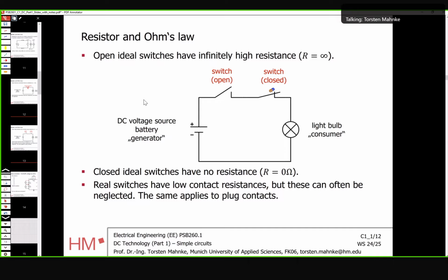This resistance was dominant. All the other resistances in the circuit were negligible. And how did I find out? After trying hours and hours, starting again, the plastic at the bottom just melted because this point became so hot. We had all the power at this point. The plastic melted; this was the reason. Everything else seemed to be fine. So this is exactly the issue I explained: parasitic resistances of wires, of any kind of contact, plugs, switches. Everything basically has some resistance.